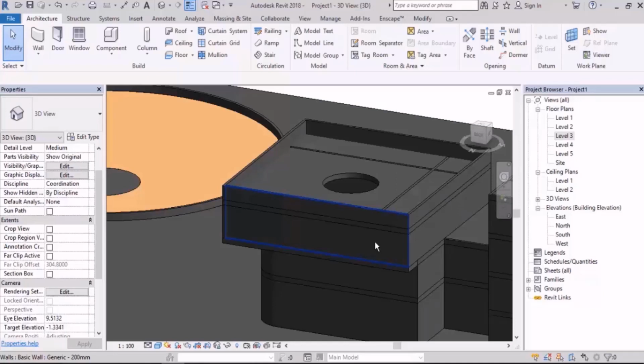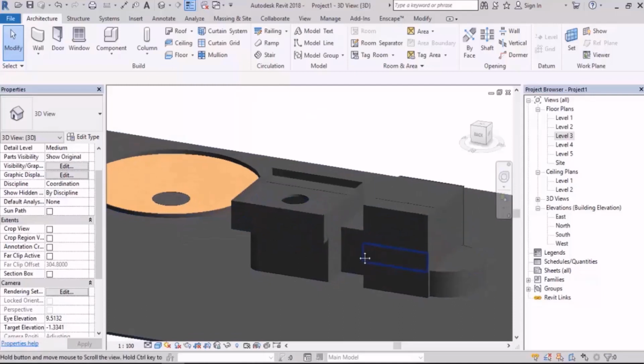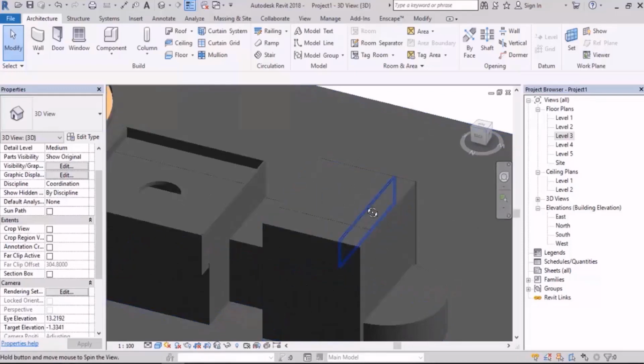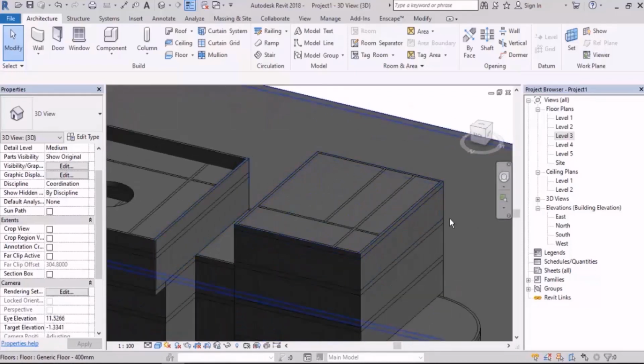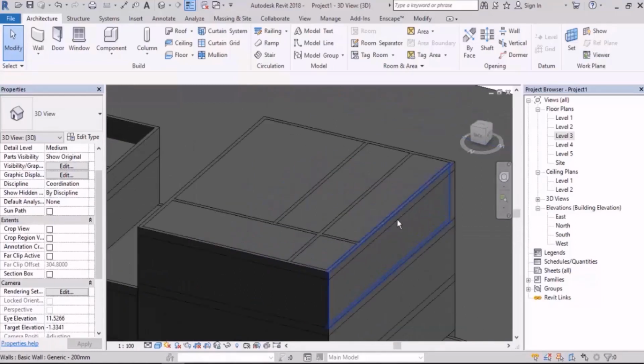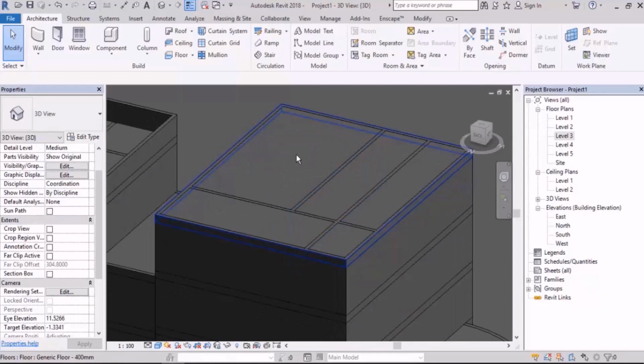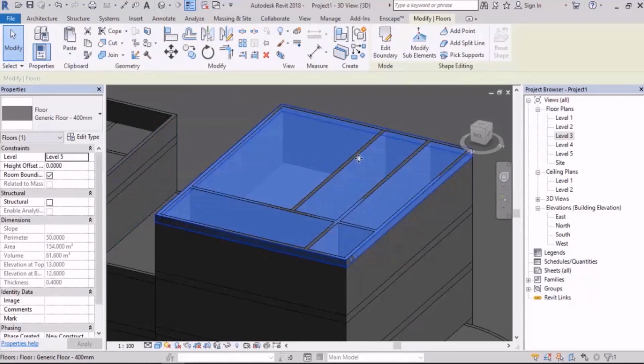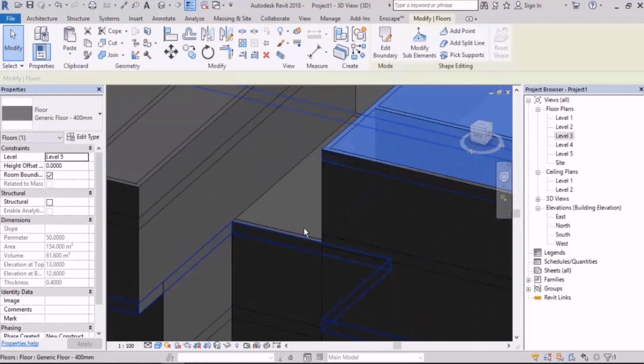So what should we do? Just like this, we go and draw it like a new wall. For example, now I want to go here and draw a shelter. In which level should I draw it? Well, if you have a big project, you don't remember which floor it is. In these times, you should select that floor, just like that, and then it shows you the level. You see, it says it's level 5. Now, for example, this one. In big projects, you don't remember the levels at all. You should just select the floor and then it shows you the level.